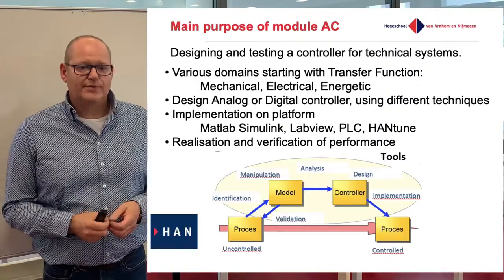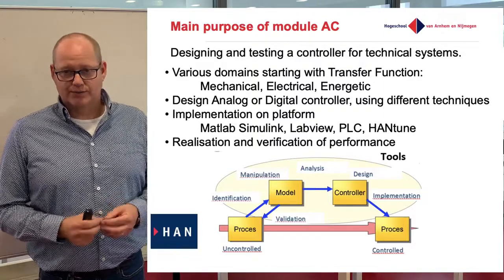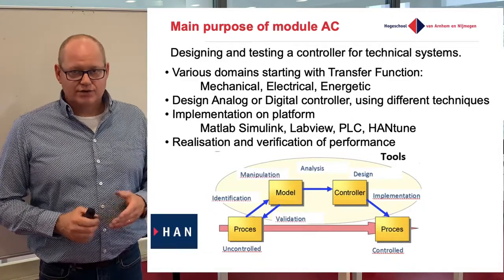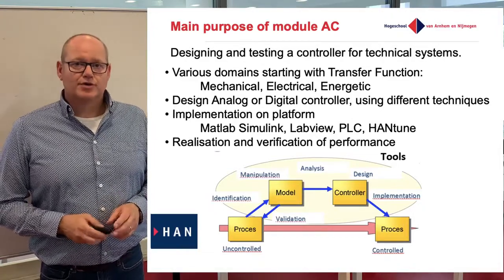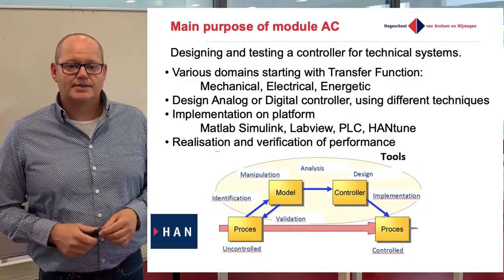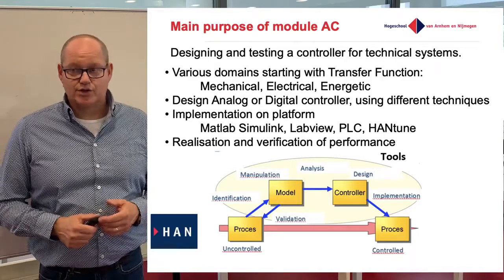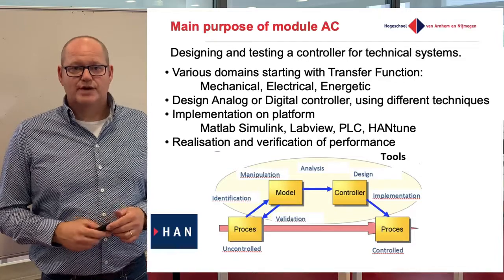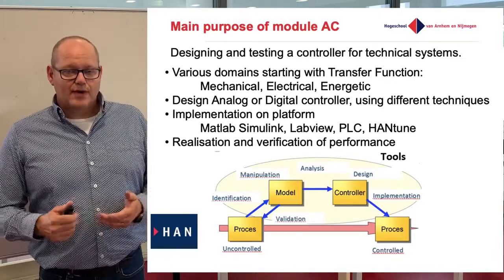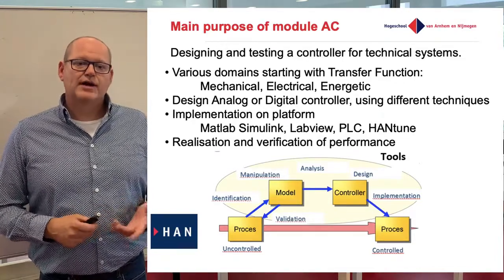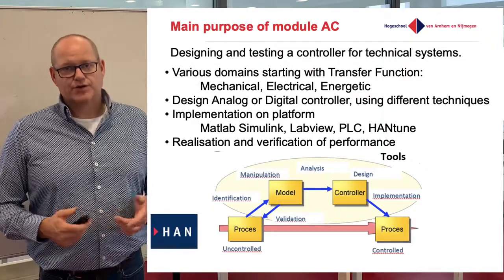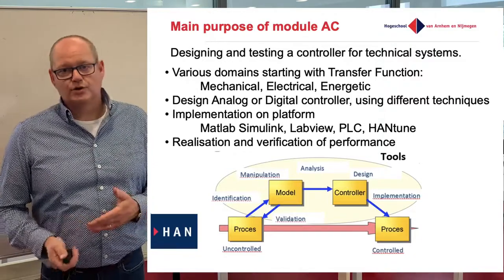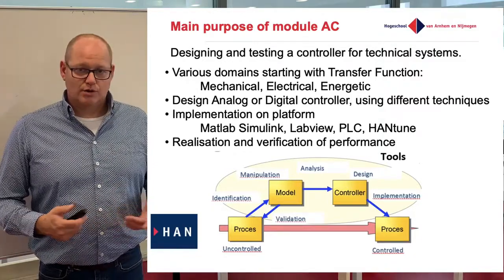So the first step is generating a model, a mathematical description of your process, trying to describe the behavior of that process. The next step is that you design a controller. Because you have a model, a mathematical model, you can design a controller in software. And after you have found the right controller, you implement it with a certain platform into the process. That platform could be LabVIEW, MATLAB Simulink, or CodeSys, for example.